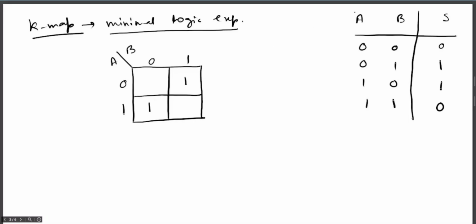And we already know that in a K-map, we cannot actually make diagonal pairs. It is not possible to make diagonal pairs. So these values have to be considered individually in order to identify the sum of product form. Here no grouping is possible, right? So for this particular one, what is the S.O.P term? What should be the term?